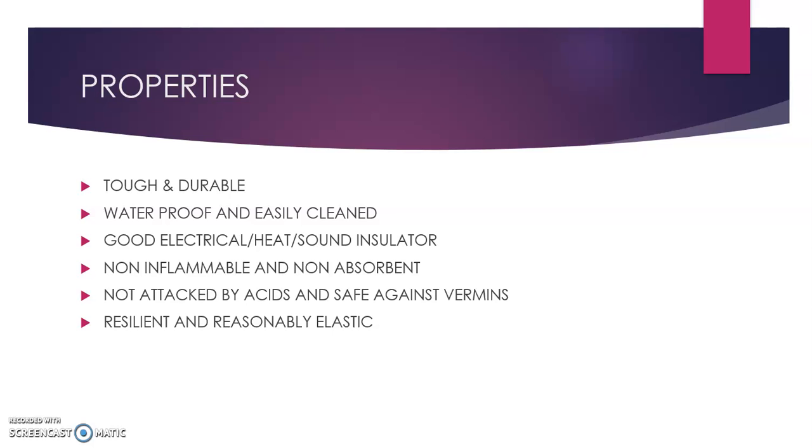Now the top part of the road will not get affected. What will get affected is the bottom part. When you take a section of the road, below your gravel and bituminous material mixture, what is there? There will be soil. Soil will easily start getting deteriorated with moisture penetration. So that's the reason we need this particular hot mix or gravel and bituminous mix layer on top, so that we protect the layers below. We make it a water-bound layer right on top. There should be no water penetration.